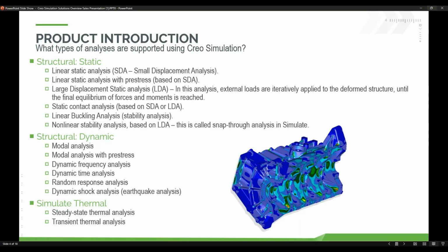I must emphasize here, any behavior or analysis numbers that you see after the object has buckled are not considered to be valid. It does not do post-buckling behavior. It will give you some results, but they are not validated or verified. It's just what happens after the object buckles.